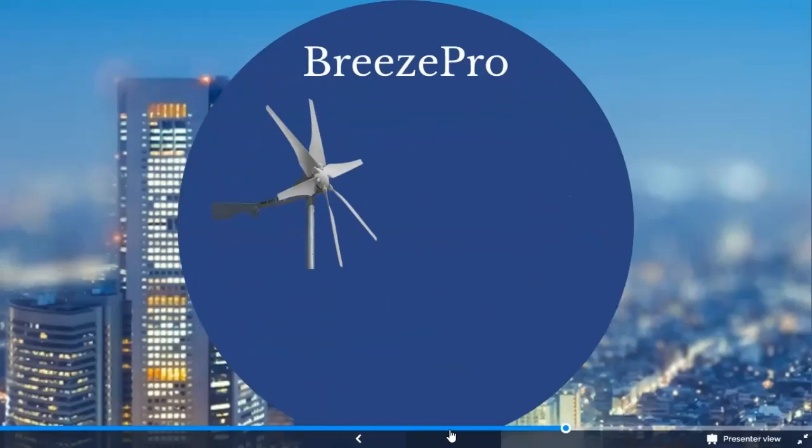Now, if you are in an area where maybe you have some extra cloudy days, or you're right on the cusp of needing to go up to the next system. For example, let's say you needed 150 watts of solar array, and so we have our 170 watt solar panels. That gives you a 20 watt buffer. But in those winter months, you might have a day or two of cloudiness.